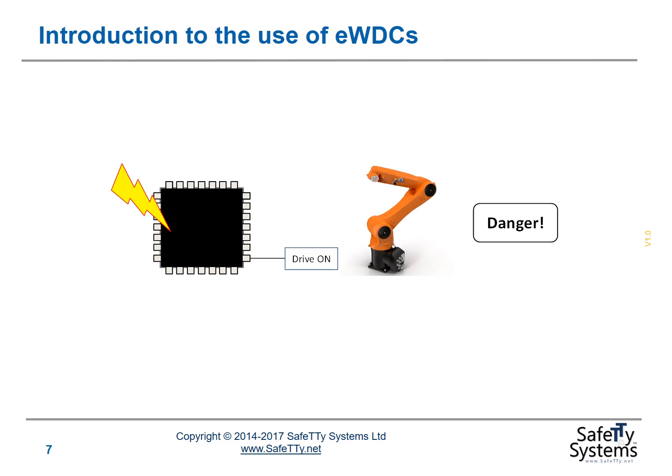Suppose we suffer electromagnetic interference, or the main microcontroller is subject to an overvoltage situation. We may end up leaving the port pins on the microcontroller in an unknown state. So we may damage the microcontroller and leave the drive enabled, and yet we have no control over the drive state by now. This is a potentially dangerous situation.